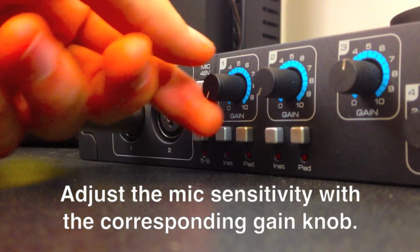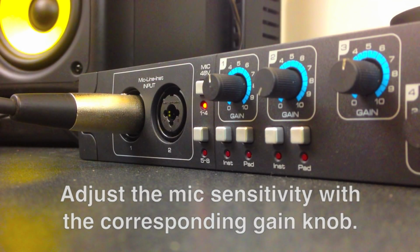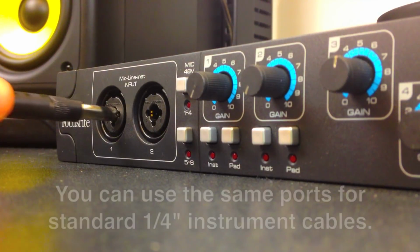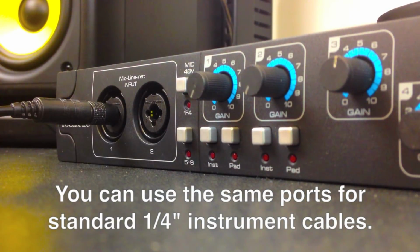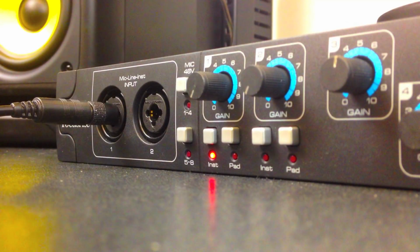You can adjust the sensitivity for each of the 8 input ports individually using the corresponding gain knobs. Note that the Focusrite's input ports also accept standard 1/4-inch instrument cables. If you're using an instrument cable, you may need to switch the input to instrument mode.